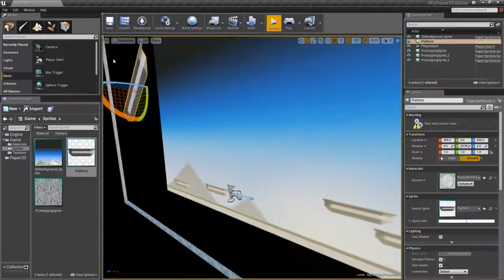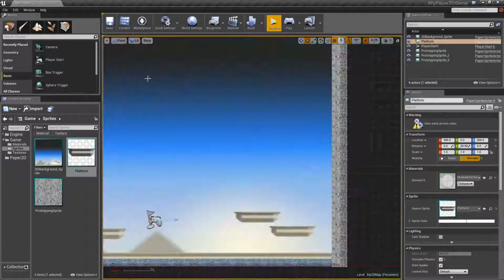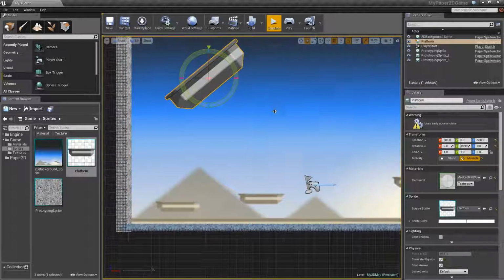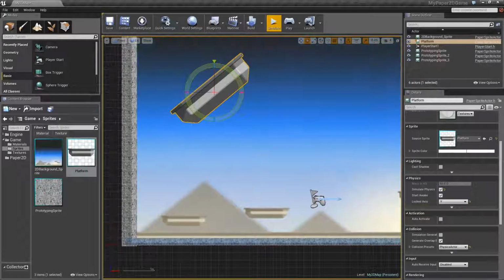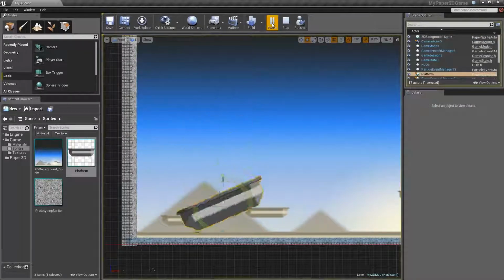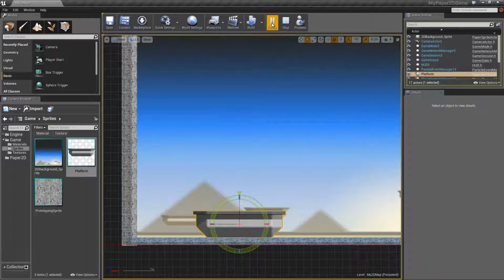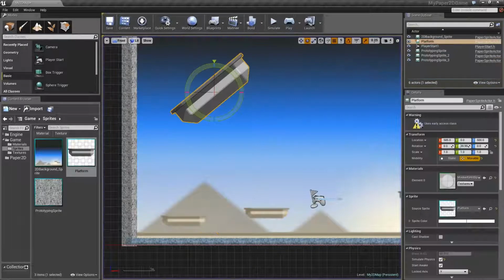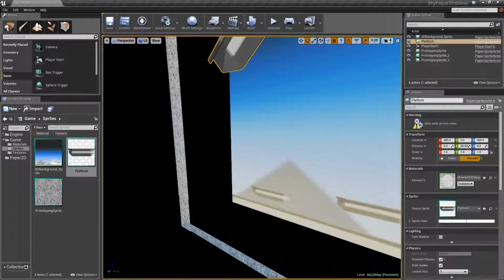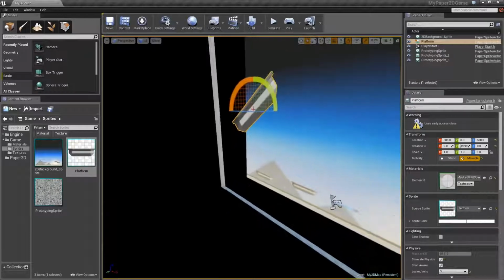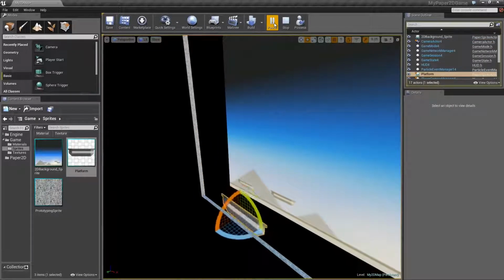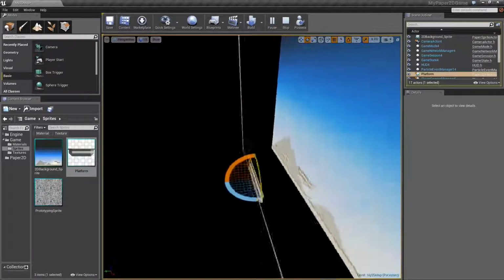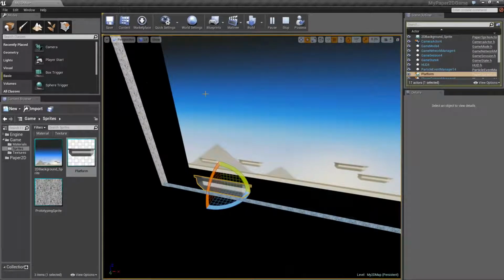So to fix this, let's go back to a front view, at least temporarily. And under simulate physics, we can lock an axis. What we're going to do is lock the y-axis. Now with that lock, let's simulate again, and boom, boom, boom, and it just lands right on the ground. And just because it's cool, and for no other reason than that, let's go ahead and take a look at that here inside of our perspective view, and we'll simulate again. Boom, boom, boom, boom. You see it just lands flat and stays aligned with everything, which is very, very cool.